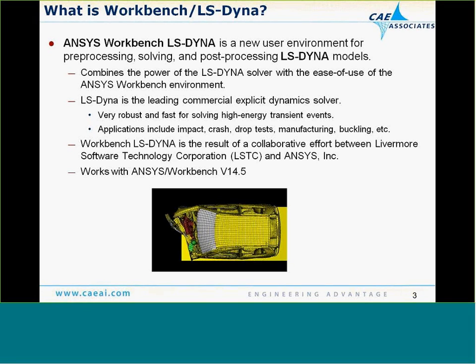LS-Dyna is the leading commercial explicit dynamic solver. It's very robust, it's fast, and it's used for solving high-energy transient dynamic events. The applications typically include impact analysis, drop test analysis for commercial electronics, cell phones, computers, laptops, and so forth, crash dynamics analysis, manufacturing problems, buckling, and so forth.